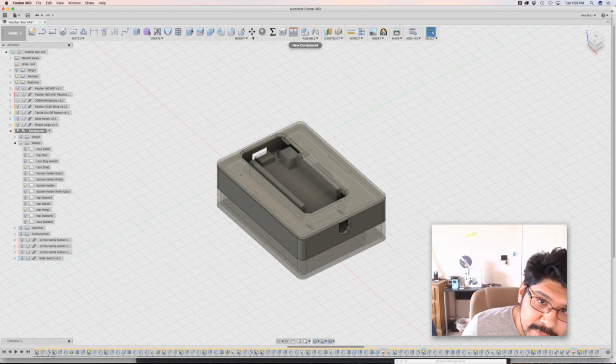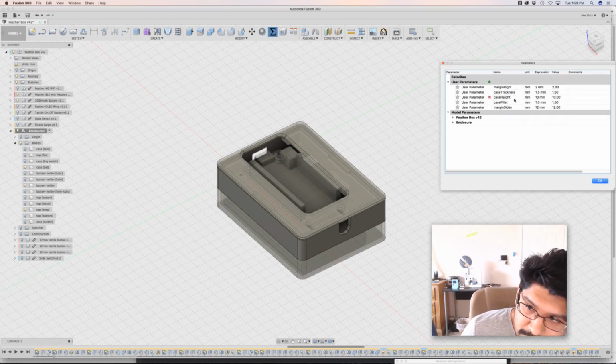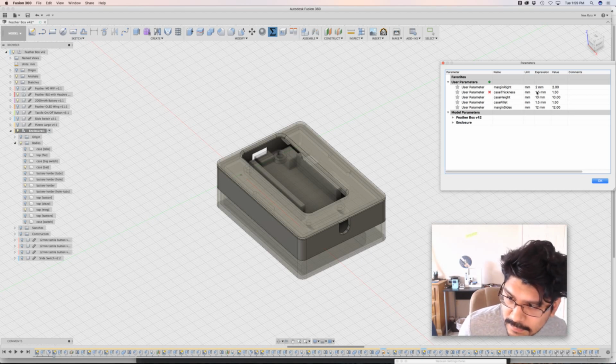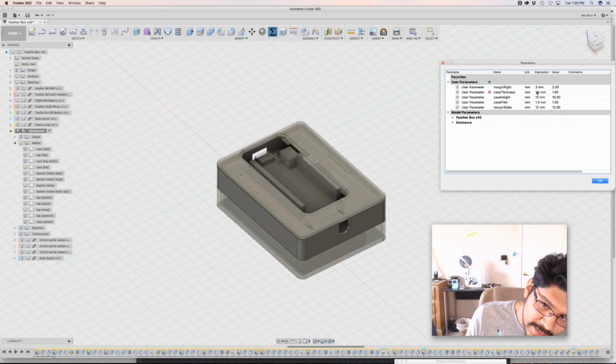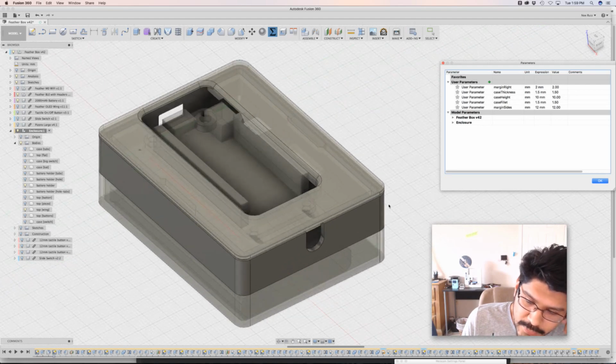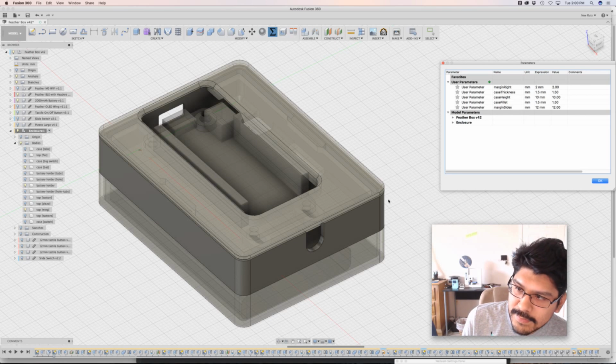Yeah, so there are some extra features I don't think are necessary. The thickness of the case, I have it set to 1.5. You could set it to 2 or 3 or something like that if you wanted a really thick case. I don't see that being used too much, because when it's 3D printed, it's 3 perimeters of a shell. So there's just 3 perimeters being drawn for the wall thickness. That tends to be pretty strong. I don't think you need it any stronger, but I have it there just because.